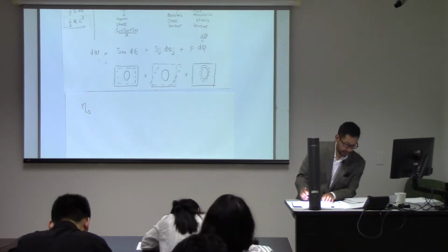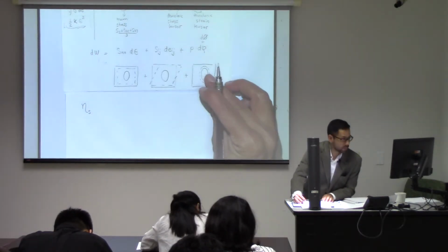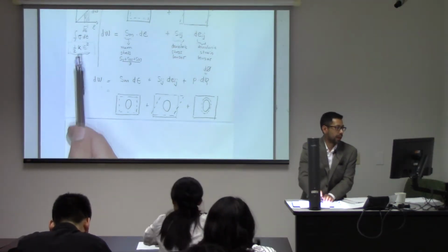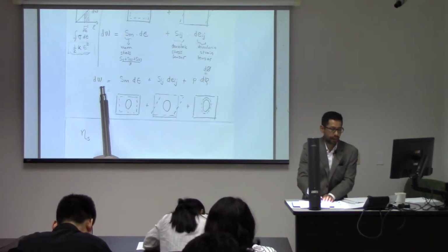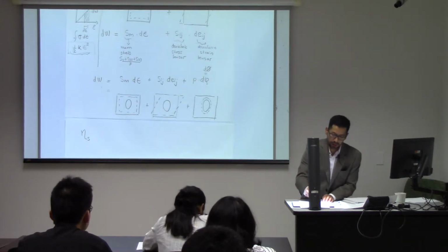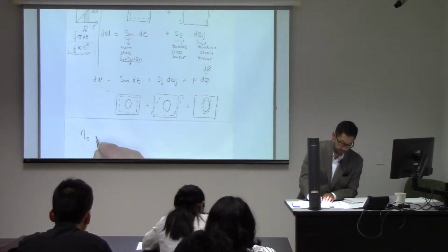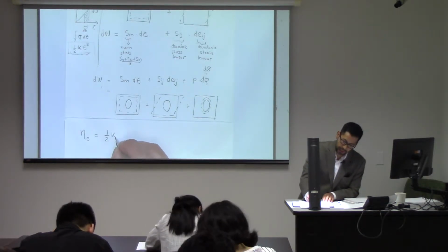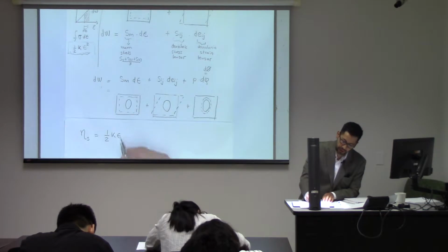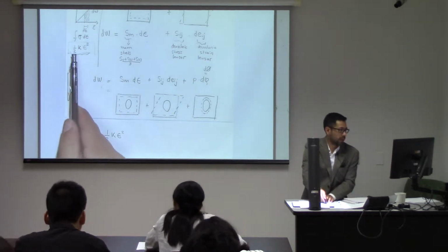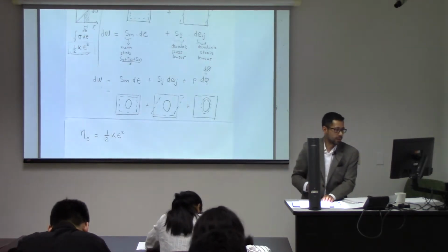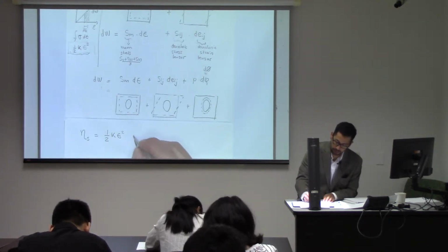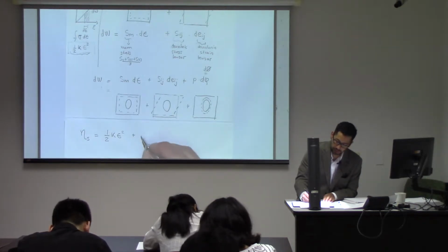And if I consider a similar equation to this one, and instead of talking about differentials, I compute the total energy, this term over here is going to convert to 1/2 K bulk volumetric strain squared, which is the same as that one, right? This one is easy to derive. The other ones take a little more work. So I'm just going to write them over here.